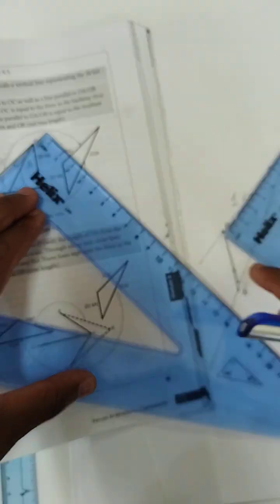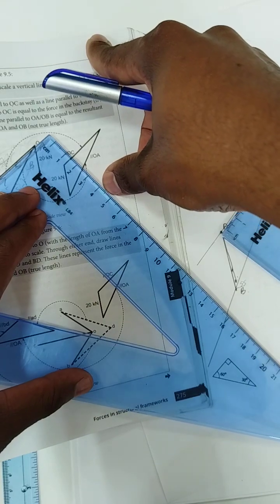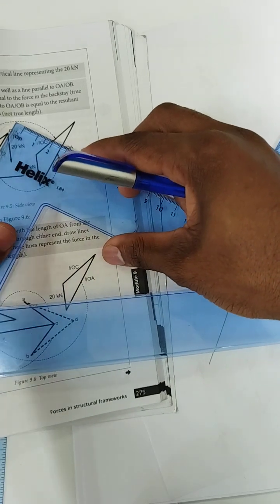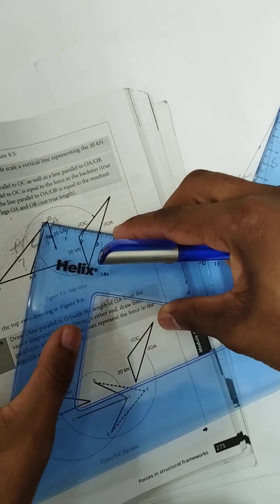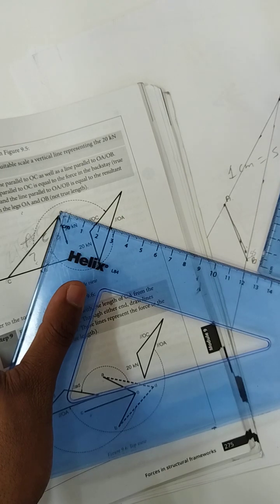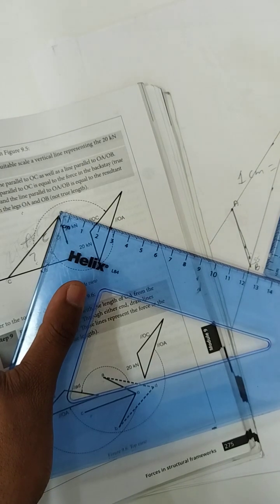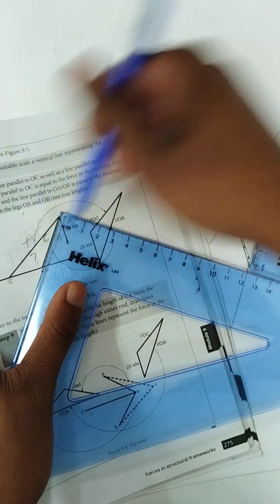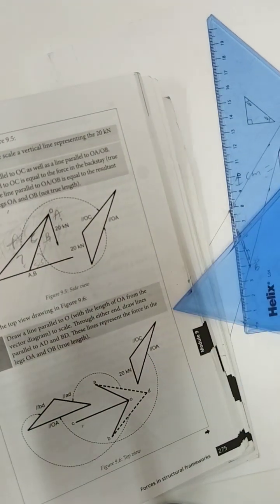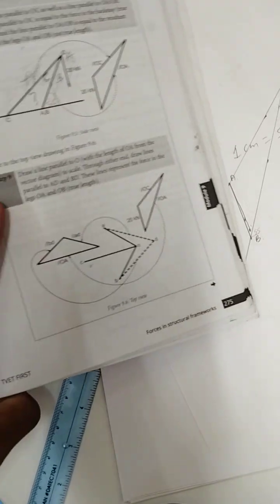So that's how you can draw the parallel line. So it's the same thing. That's when you don't want to use your protractor, you can draw it like this. Then to find the parallel line of this, let me put the book straight as well so that we don't experience the same thing. To draw the parallel lines of this, you put your ruler like this, and then this line now will be parallel to this. So that's how you can construct this line without using the protractor. Yeah. Then from there, you measure.